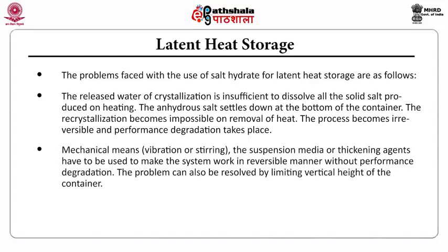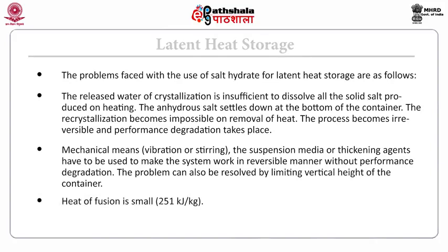Mechanical means, vibration or stirring, the suspension media or thickening agents have to be used to make the system work in a reversible manner without performance degradation. And this problem can also be resolved by limiting the vertical height of the container. And also the heat of fusion is small in this type of storage.